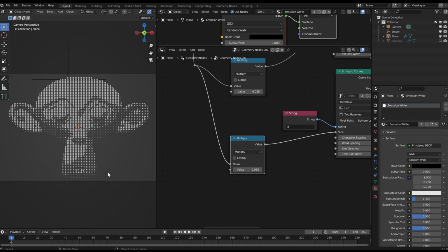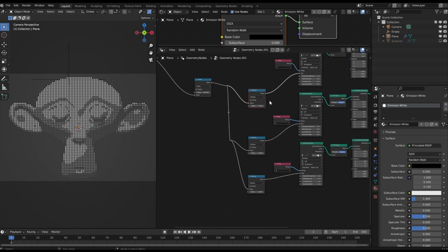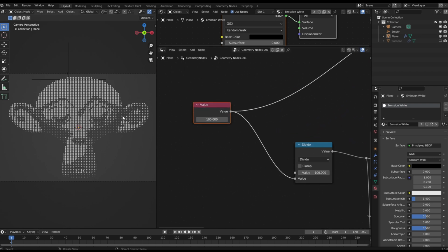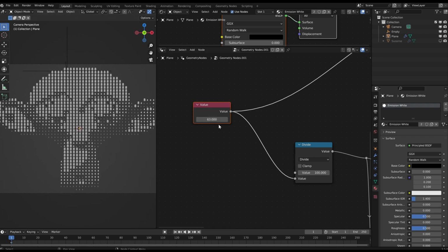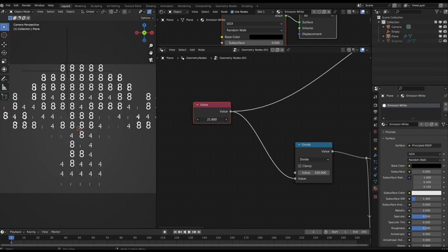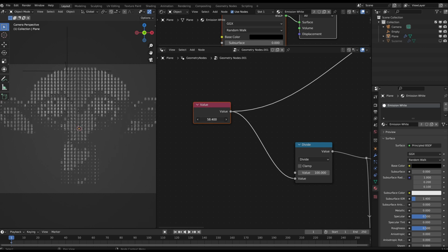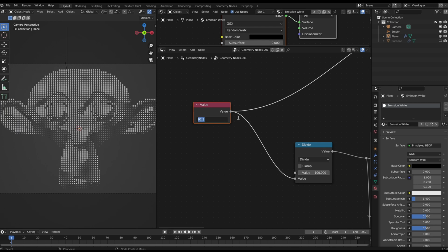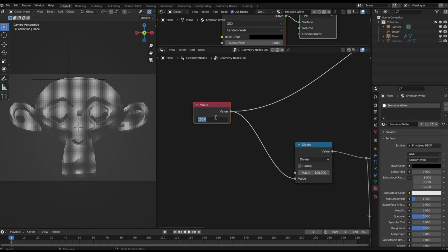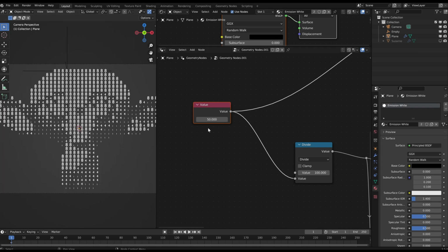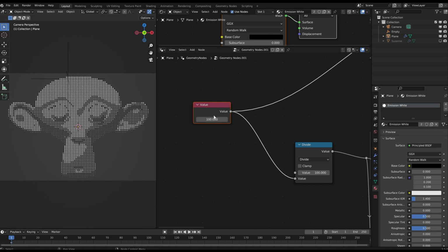And now you can already see this results in way more contrast because the 8s are larger and cover more areas which are bright then due to the number surface. So this is the reason why I did it 3 times, because now you have individual control for everything. And because I bound it here to the grid size, you can now change the grid size and then the numbers will change their scale procedurally and adaptively, and it will always be the same grid basically with the different resolutions. So let's keep it at 150, for example, which is more detailed, or 50 to be more rough and pixel art style. But let's keep the default 100 where I started.